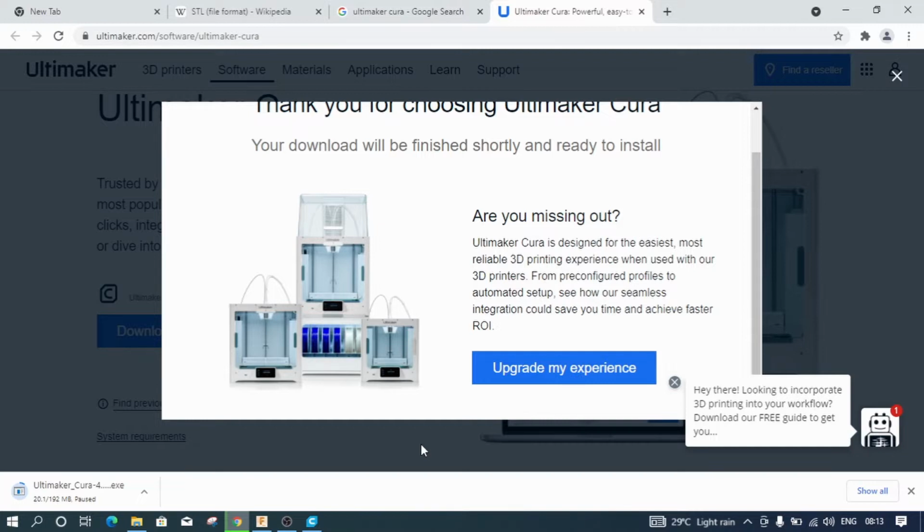Please checkbox that also, and in the file types that it asks you to support, please checkbox the OBJ, STL and 3MF file formats. And lastly, during or after the installation, it asks for Adafruit enabler. Please enable that as well while you are installing Ultimaker Cura.